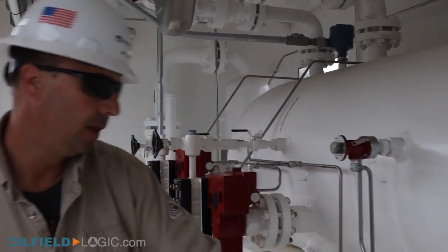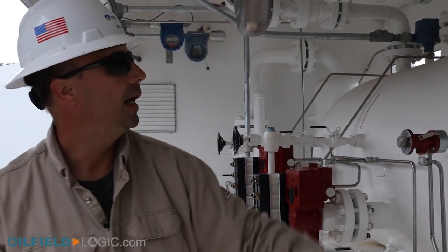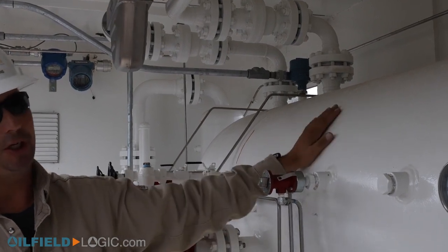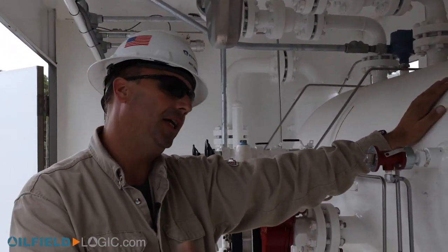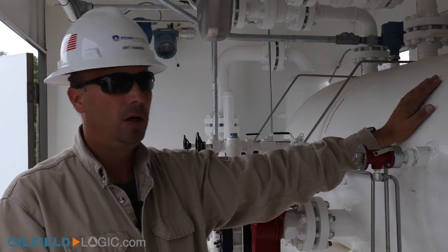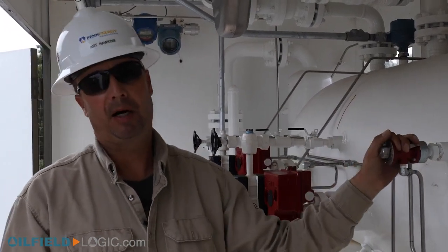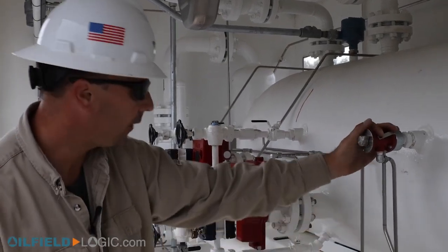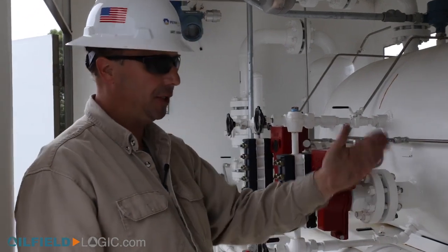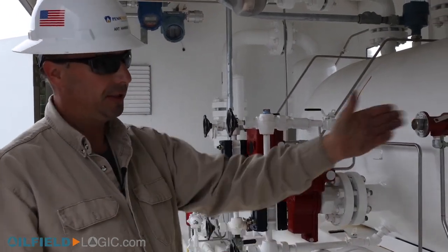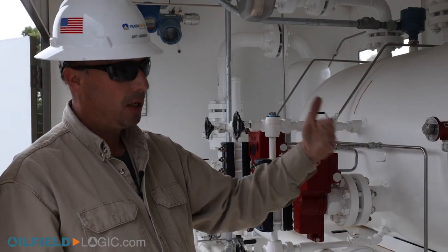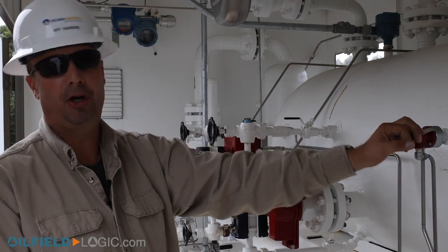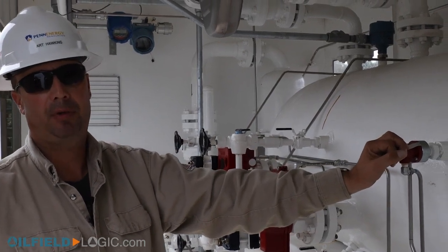We have a temperature readout here, and this is a second thermostat that we use to control temperature in the separator itself. Based on the amount of water, oil, gas, that will vary by the amount of flow, so we can adjust it up or adjust it down as needed. We do have safety shutdowns also in relation to that, where for some reason our burner or these thermostats weren't working properly. We will shut down on low temperature, high temperature. It'll shut the fuel supply off to the burner and send an alarm up to the operator.